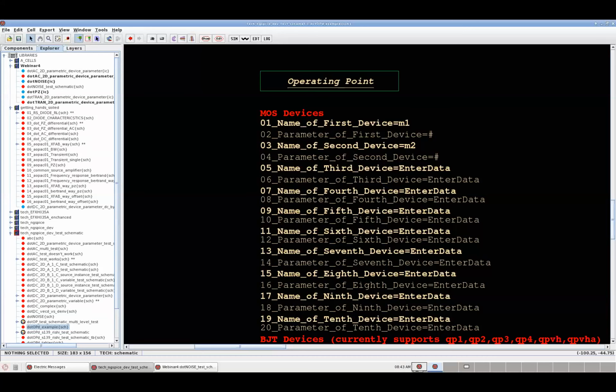This is in case of circuits where you have some settling time needed before you settle down to a stable DC bias condition, and then run AC. Okay. I think the bandgap here, the circuit under test, has a startup circuit and it takes time to start. So how could we do AC analysis without giving the simulation the information about at which time it's going to solve the AC?